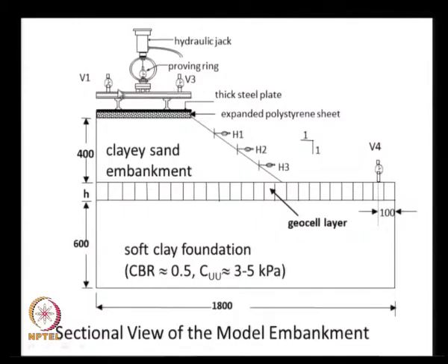We measured 3 vertical deformations. There is one dial gauge just behind this proving ring, and there is one more dial gauge here, and then the horizontal deformations within the height of the embankment, and then the heaving of the foundation soil was measured at the far end of the tank through this dial gauge.